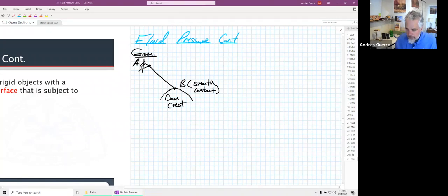Well, one of the people I was working with that had been there for like 30 years said, why don't we change the angle of those gates? We're having these issues with the earthquakes failing these gates. Well, it's because the gates are basically straight up and down, and all our fluid pressure is acting perpendicular to those gates. Well, if we change the angle, that means we change the angle of our fluid pressure, and we're actually going to get pressure that's going down into the dam.